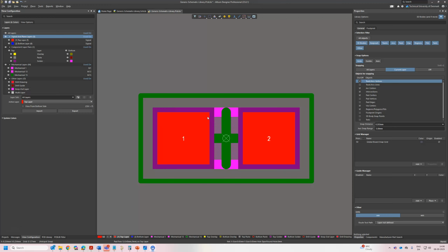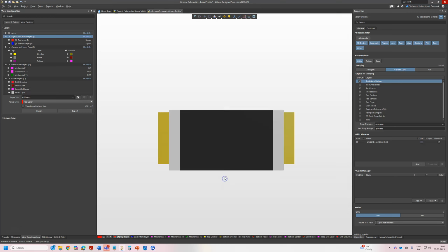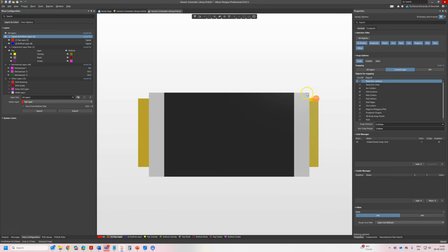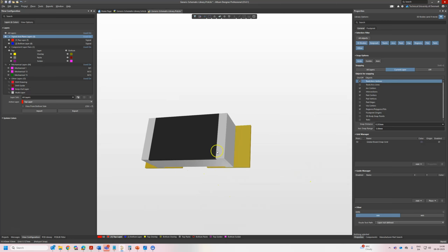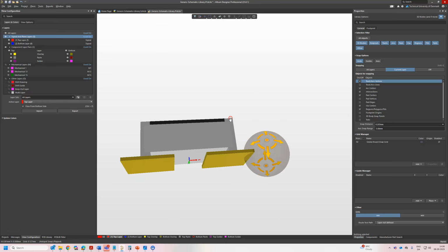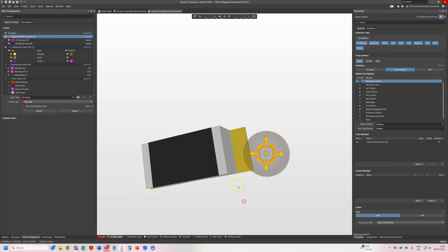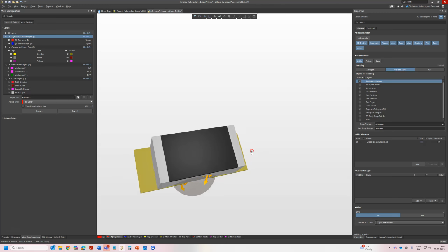The manufacturer assembly layer basically shows the exact outline and details for your resistor. So basically if I click 3, it will show the exact size of my resistor. So this edge from here to here to here to here. Here we can also see when we press 3 how our resistor looks. So we have a nice spacing here. We have a nice spacing here to solder.